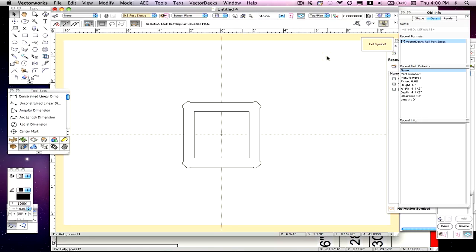So let's go ahead and make those changes. First, go ahead and select the width. And let's set that width to 3.5. And now go ahead and select the depth and make it 3.5. Now we have everything we need. We need the proper dimension. So VectorWorks knows that this particular sleeve fits over top of a 3.5 inch by 3.5 inch post, and it's going to base its calculations on that.